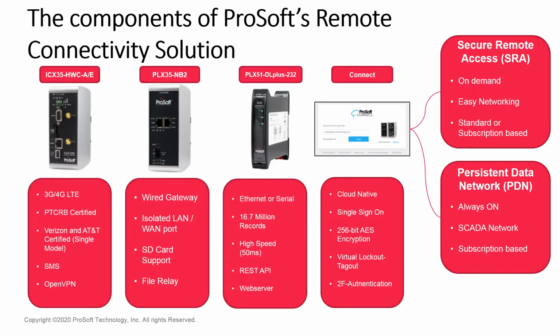One of the key advantages we offer with our gateway is add-on instructions to ensure integration into a Rockwell connected architecture is simple and easy. These add-on instructions allow you to do things like generate SMSs, or get access to the gateway's diagnostic data, which can then be mapped to variables within the PLC and displayed on your SCADA system, for example, or you use that to make certain decisions on how to operate the plant or the process. We've also got a wired version of it.